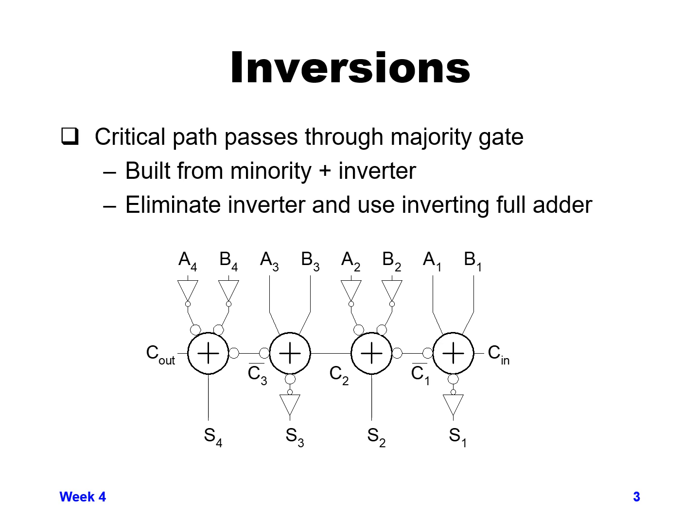And for a smaller adder like an 8-bit or maybe a 16-bit, the speed up of getting rid of one inversion per stage might be good enough for you. Typically for a 128 or 64-bit adder, you're still going to want something else to speed you up some more.